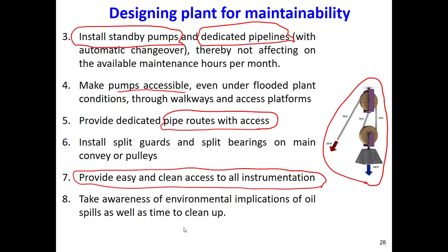And also, we have to consider the environmental impacts of maintenance. Let's say when you are cleaning a compressor, a valve, or a pump that was operating with toxic material, when you open that valve or that equipment, there might be spills of those toxic materials on the floor, or it might contaminate the working environment. So we have to consider those things when we are going to do the maintenance.